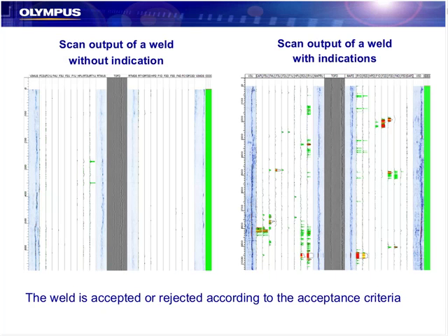So this might be what typical output would look like if we had a scan with no welds. Typically we use color coding and some other tricks so that we can look at a full volumetric scan 360 degrees around the weld and immediately key in on areas that might need investigation or sizing. We'll look at those color codes so they make a little more sense. But here you can see this one. We got some reds and yellows, some other things that are going to bring our attention to those defects to do further analysis.